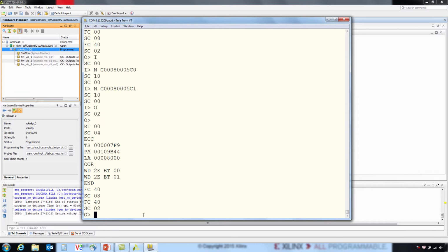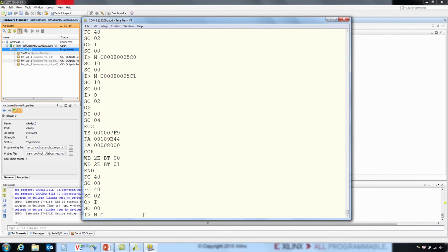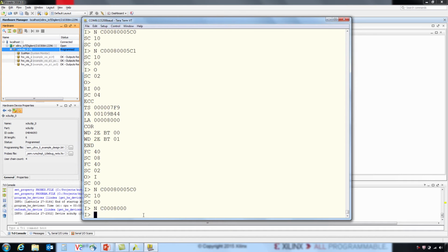Now let's try test 3, a correctable 2-bit error in a single frame. Again, some SEU are small multi-bit errors, but not involving many bits. So again, I'll do this without the queries. Go to idle, inject. Oh, I made a mistake.